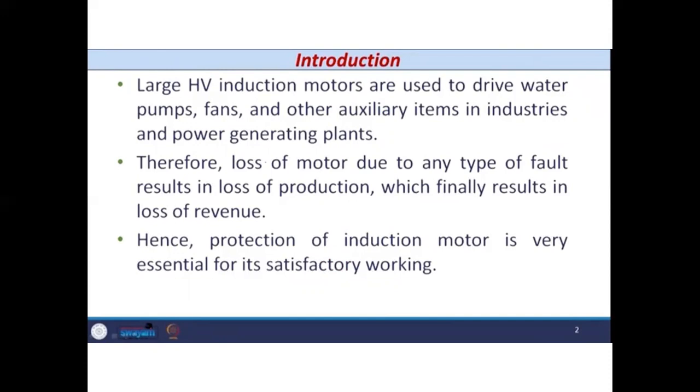All types of electrical and mechanical faults should be considered. In electrical faults, we have discussed different phenomena, starting from overloading, the overcurrent, the short circuit current, the negative phase sequence, the phase reversal, the stalling, the phase unbalance, and under voltage.